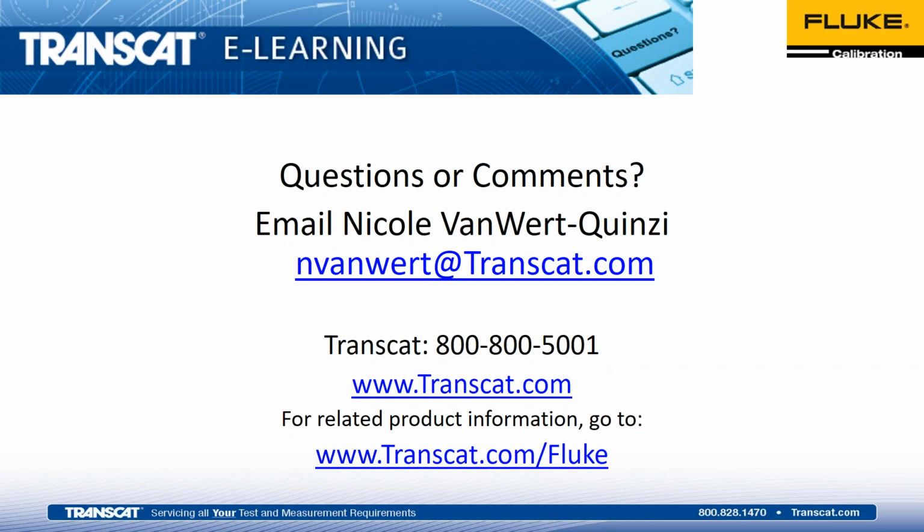How often do I need to calibrate RTDs? That's kind of a loaded question. It all comes down to your process and risk versus recall is how I advise most people. Again, how critical is the uncertainty? How much typical shift may I see in the process versus what's going to cause a catastrophic rework or recall? So you kind of have to weigh that versus the uncertainty.